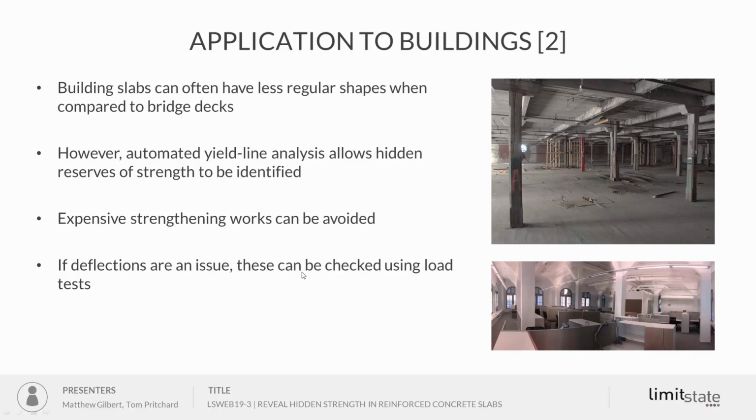The other thing to say is if you're dealing with an existing structure, then potentially you can deal with the serviceability requirements via simple load testing. So you could actually check that the building satisfies those constraints that you might be working with, for example, by filling up water tanks and exerting load that way.